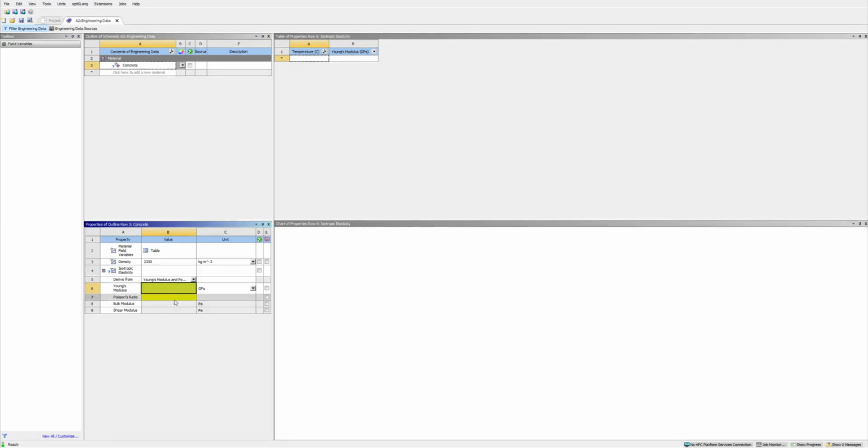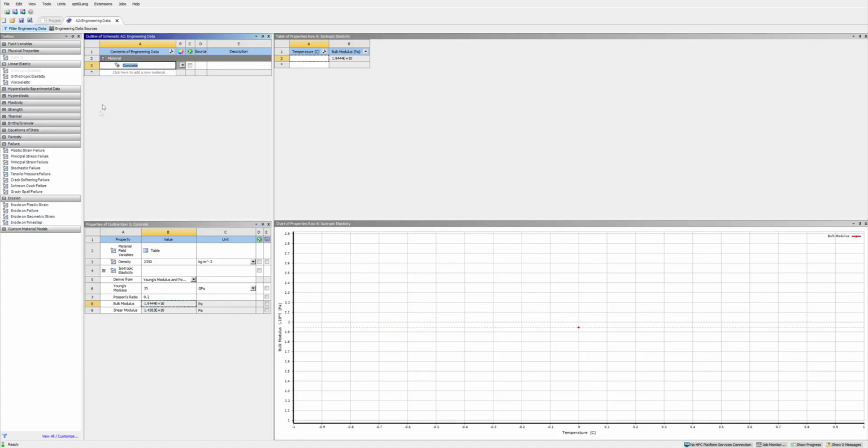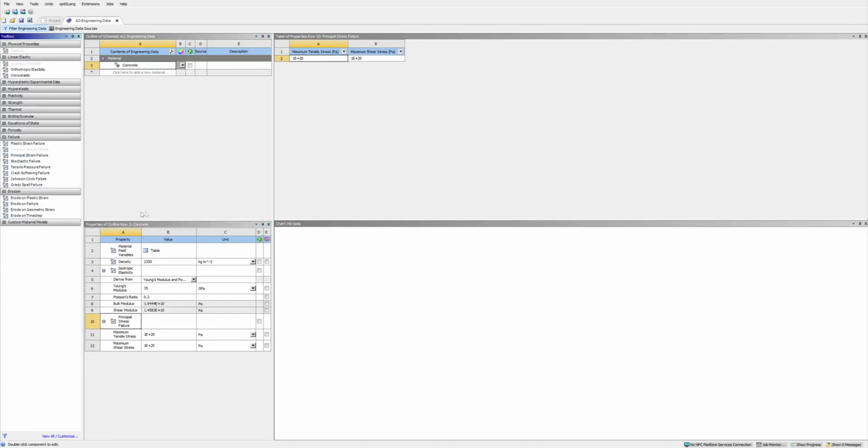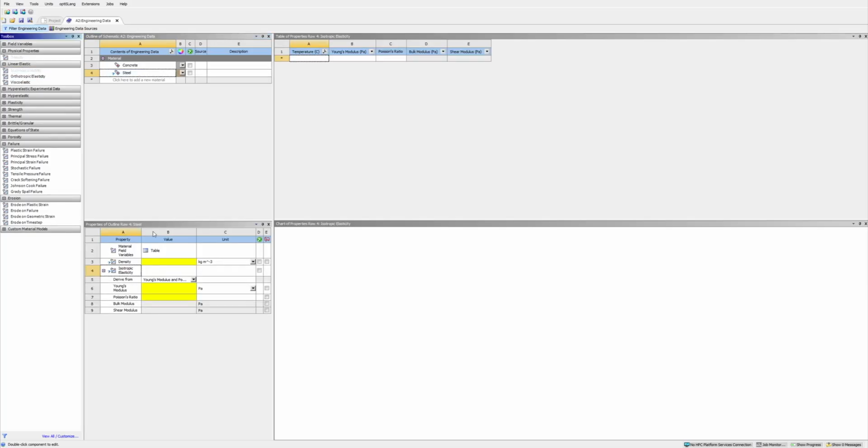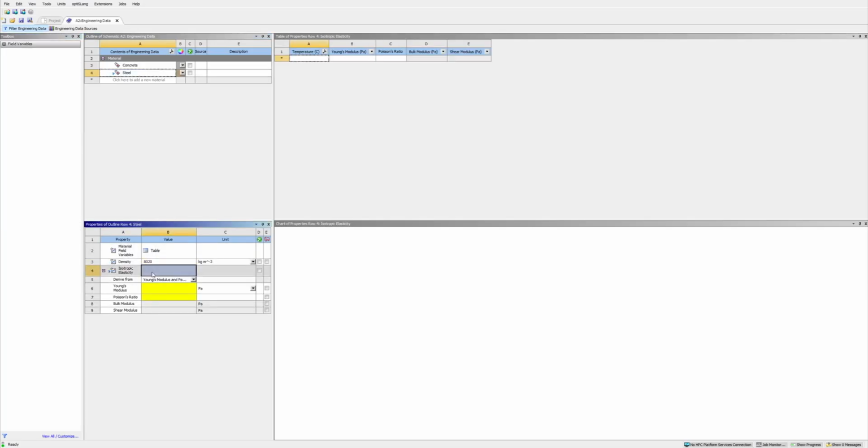These properties I am entering are from our tests in the lab. We will use the principal stress, the first principal stress, to initiate failure. We will use a very large value for maximum shear stress so that the specimen does not fail under shear loading. The fracture energy value is a guess at this point. We will also turn on erosion. For the steel, we will just use a linear elastic material without any failures.